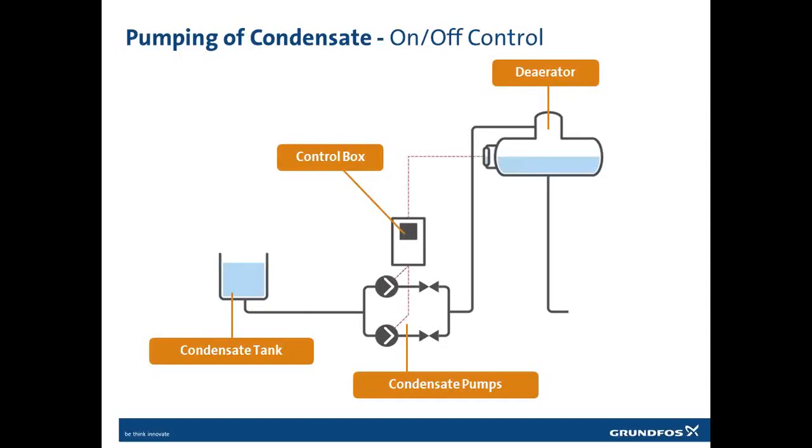One thing to think about on condensate systems is that the water is hot, 200, maybe 210 degrees Fahrenheit, and that is challenging when we are talking suction on the pump. So we need to be aware of the NPSH, and we will get back to that later.